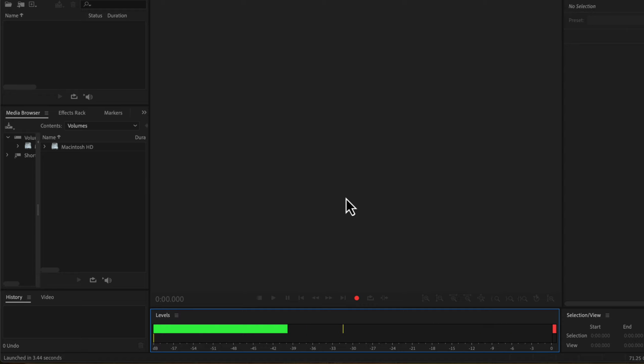If you can be in the range of -18 to -6 dB, you will have enough room for post-processing and will get high-quality audio after processing. To achieve proper levels in the meter, you have to talk from a proper distance, usually 4 to 6 inches from the microphone. You also have to adjust the gain in your audio interface or microphone to hit the desired level in the meter.